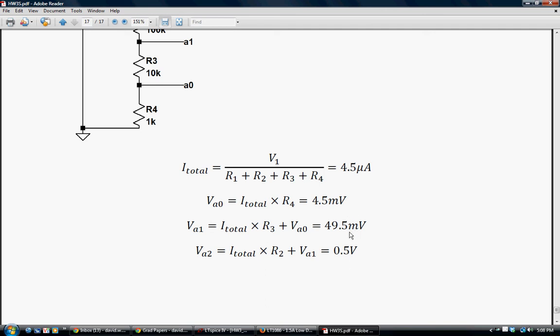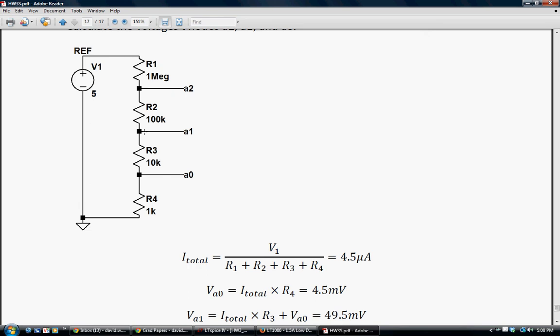And so you can see a logarithmic progression with some simple resistors, where if I was to use this as an A to D, not only am I converting it from an analog to a digital signal, but I'm also taking the log of it. Taking the log of something on a digital computer is actually quite numerically intensive.